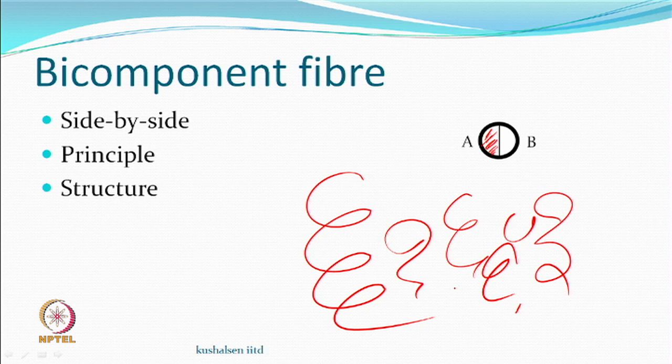So, one of the interesting products which we had was the acrylic bicomponent spun yarn system, where you would say it is a bulky yarn, right. But if you are very smart and the difference between the swelling capacity of A and B is so large that they actually make a beautiful helix, you can see the helical structure, a little bit of a difference. So, you cut them into staple fibers and then mix them and make a yarn out of it, like wool. You say the inspiration is from wool. Wool is also a staple fiber. So, you make a staple yarn, just like wool. Any problems? There is no problem. Go ahead, do it.